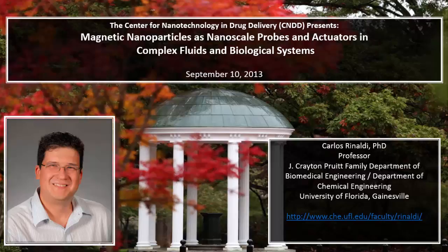And the temperature determined from these measurements is about 21 degrees C, which is lower. This is the rheometer data, and this is the magnetic data, which is lower than the gelation temperature measured using a macro scale measurement. So you can superimpose the curves if you shift them, and there's a difference of about 3 to 4 degrees C in the gelation temperatures.